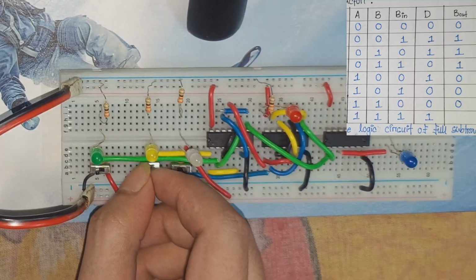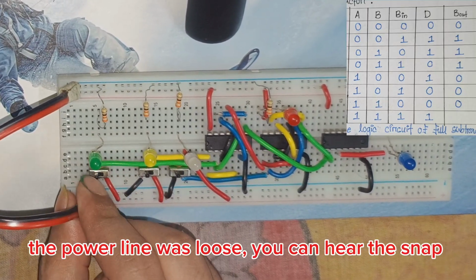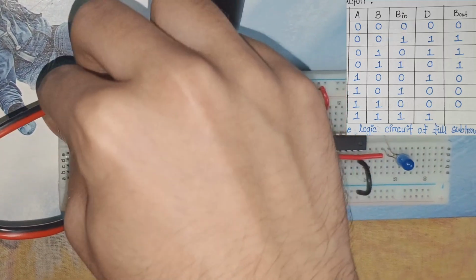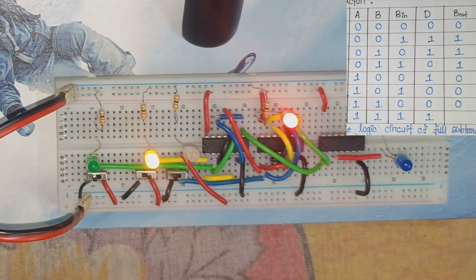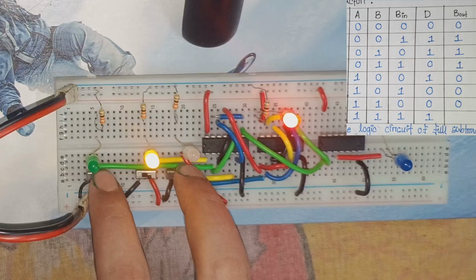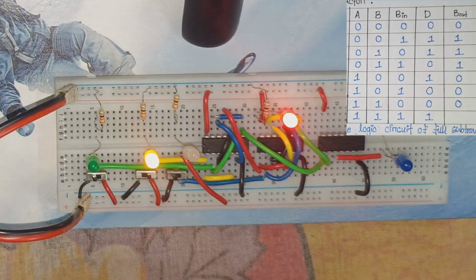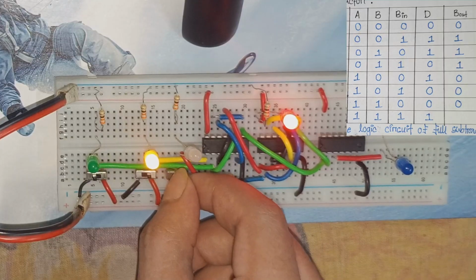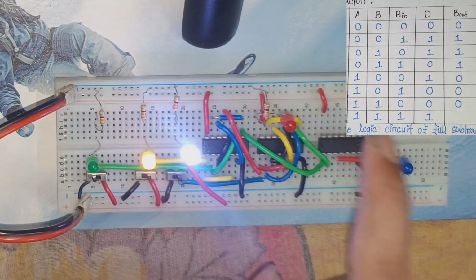There is a loose connection problem and nothing serious here. Due to the loose connection it's fluctuating. Okay, so at the fifth row the A is 1 and everything else is 0. So when A is 1 and everything else, I mean every other inputs are 0, the difference should be 1 and borrow should be 0. Simple. Borrow out, this is borrow out, this is borrow in. Okay, at the sixth row we give A high and also the borrow in high. So when we give A high and the borrow in high, we get difference 0 and the borrow 0.